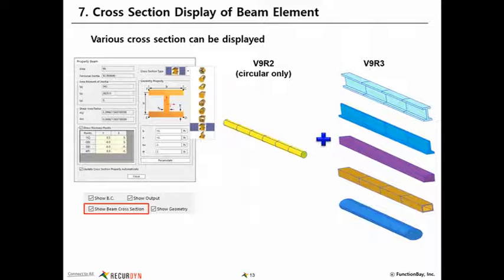So some of that will be done automatically. I know that I've had meshes that did not perfectly align, and RecurDyn will go ahead and make some adjustments so that at that one point where you've defined that patch set, it will be the same size, but then there can be some gradation from that point.